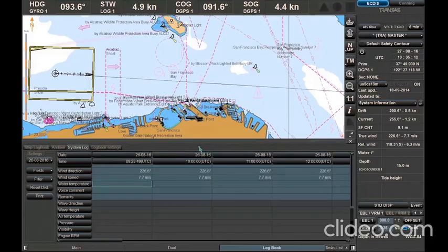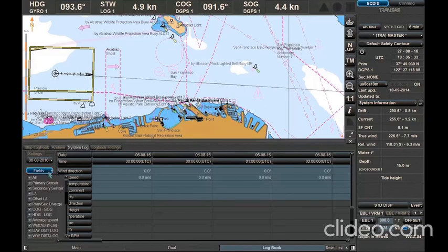The system log file is created every 24 hours, with the change of date by UTC time. Select the required date from the Settings group. The current date is set as default. To change the content of the system log, click the Fields button and uncheck the checkboxes of any unnecessary event parameters.